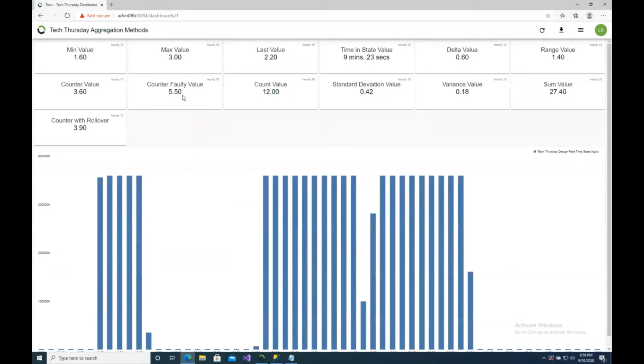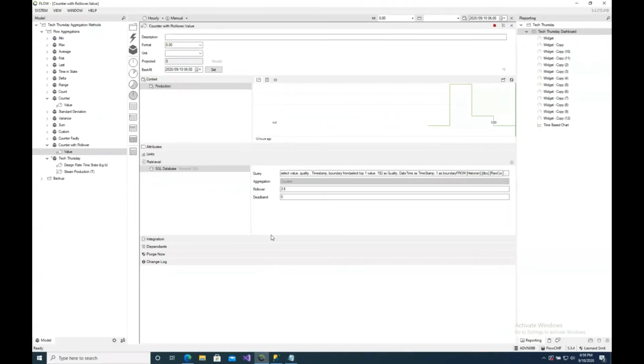It's something we get quite a lot on tech support, counter values that are quite massive. And 9 times out of 10, it's because the totalizer value inside of my historian is not incrementing. There is a gap inside of that. We can either go and fix that at source in the actual process condition, or we can add a deadband to say, you know what, let my totalizer at least change by 0.3 or 0.4 before we go and have that aggregation method applied. Cool.